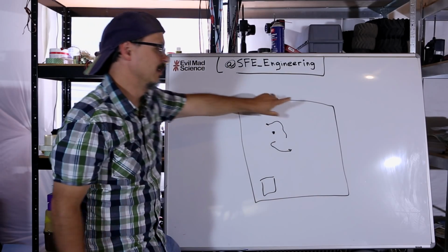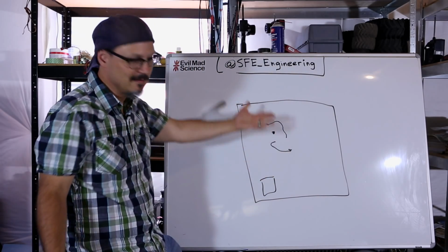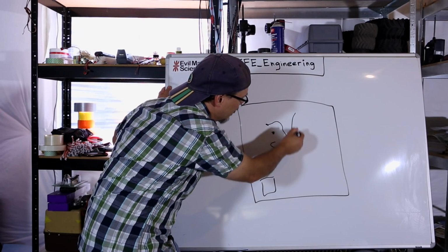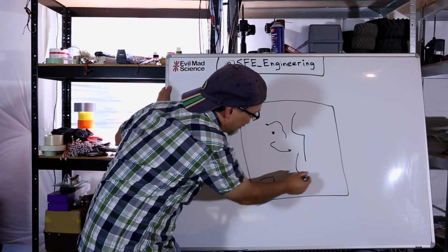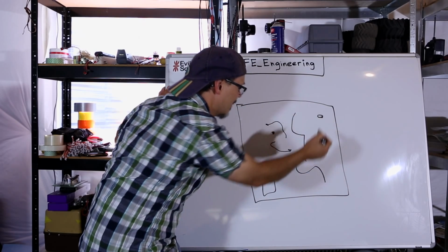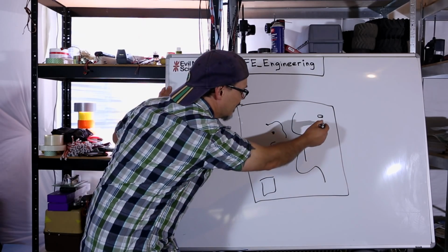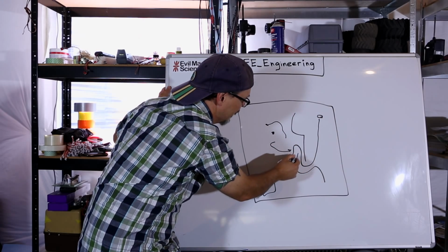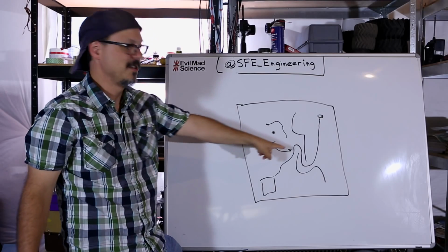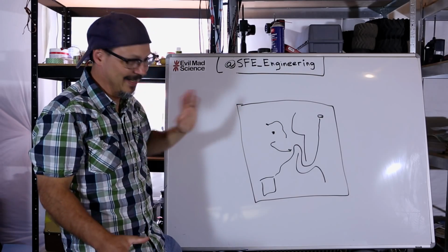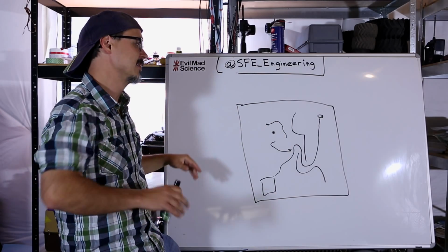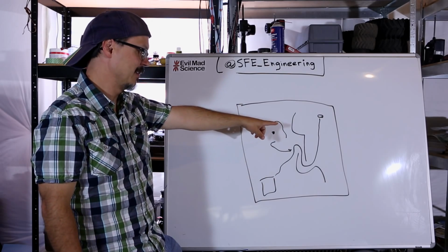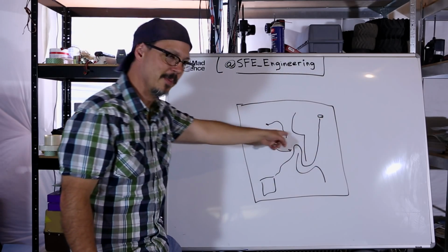And of course, it'll use the path of least resistance. Plan on that. But if I've got a whole slew of other traces here, and I'm powering something out here, what's this return path going to look like? Well, it's going to follow the copper kind of, and you want to watch for stuff like that. For low current stuff, it's not too bad. You can make that compromise. But if I'm drawing 30, 40, 50 milliamps to something out there, I don't want a return path that looks like that.